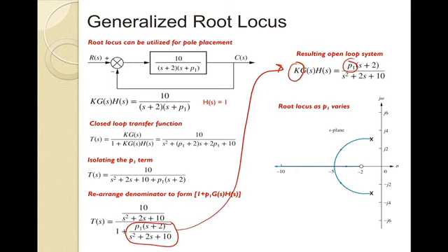And so what we're going to do is look at this characteristic down here, and when we solve that, we're going to see, first of all, s plus 2. We have a 0 at -2, and then the original starting point, we can use the quadratic formula for that, substitute the two values of s, and we're going to get those as our starting point. So here are our poles. That's essentially our starting point.